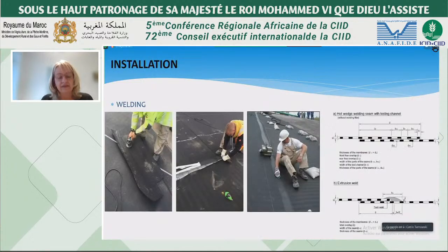The installation of the product looks different nowadays. We had already seen a very small welding device, and you can see a small welding device in the right picture as well. The left picture shows the preparation of a test seam, because you want to assure that your weld device is functioning properly on the site, that there is sufficient energy to do the welding, and that the environmental conditions allow it. And then the welding on the site can begin.